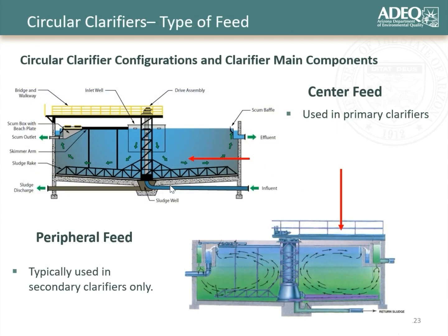As long as they're operated well and within design parameters, they should perform their duty. But think about the circular clarifiers. There are multiple different types of feed systems for these, really just two. One is a center fed system in which the wastewater enters the center of the clarifier and then the flow divides between the two sides and will eventually overflow the weir where it leaves.